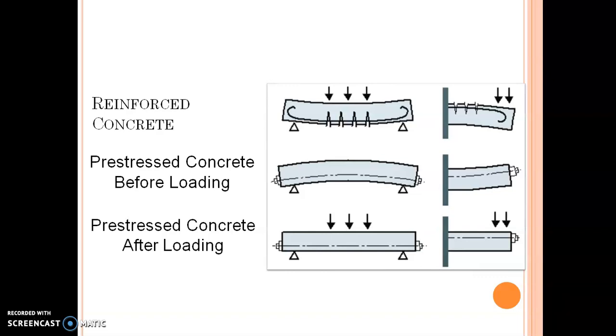Whereas in the cantilever beam, we have applied the force in the tendons above the CG. When you apply force in the tendons below the CG, it creates tensile forces at the top and compressive forces at the bottom. Why do we have this difference between these two? We will see. As you know, in a simply supported beam, as load is applied, compressive forces are created at the top and tensile stresses are created at the bottom. So, to counteract and nullify this, we apply force in the tendon below the CG so that it creates compressive force at the bottom and tensile force at the top.